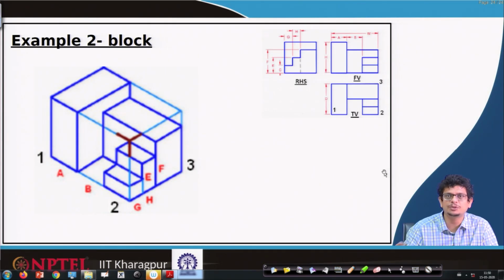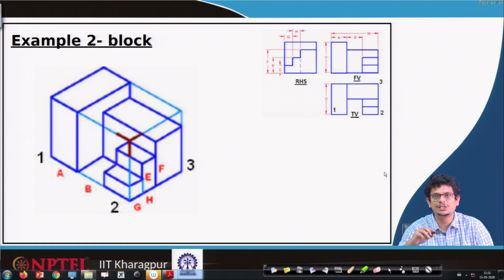But the basic concepts behind these isometric drawings are, first of all, identifying these principal axes, principal planes, and suitably transferring these lengths from each of these views onto these principal planes. Through an intuitive approach, we will join, remove the lines and get the object. Once we construct that, we have to re-verify whether it is matching the views.